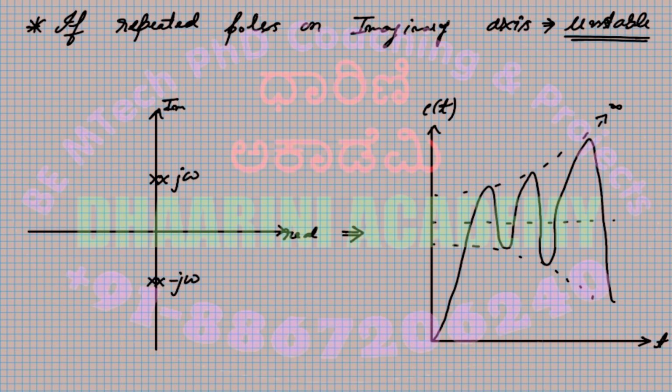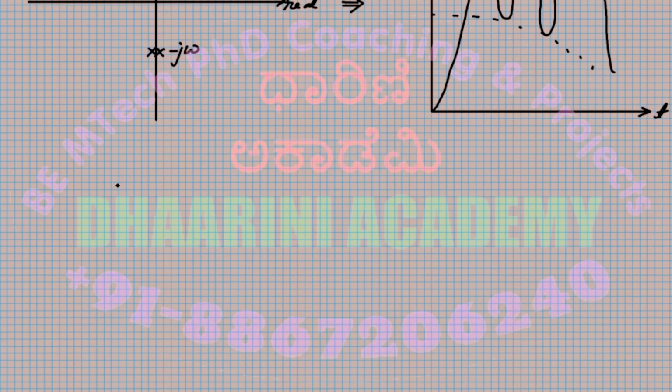All right, but normally what happens is that the system's characteristic equation will be, if it is s to the power 2 or s to the power 3 or something, yes, you can solve it using a calculator to find the poles, correct? So I can do that. Let's take an example. This is the example: identifying the position of the poles by simply solving an equation. Okay, so let's try to do that.